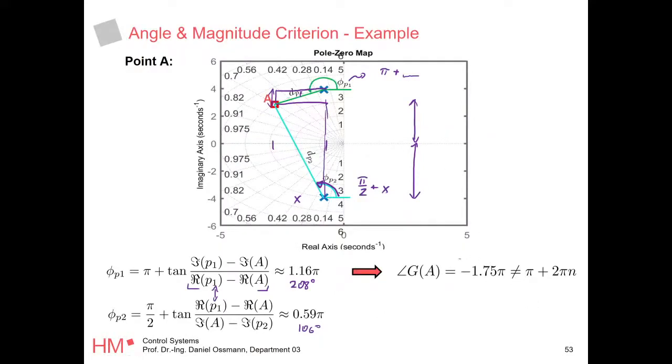And we realize this guy is not 180 degrees, right? It's actually closer to 2 pi, so to 360 degrees. It's definitely not going to be on our root locus curve, right? But yeah, we know that from the simple root locus curve of this PD2. But here is the validation, or the confirmation, that this point is not on a root locus curve based on the angle criterion.